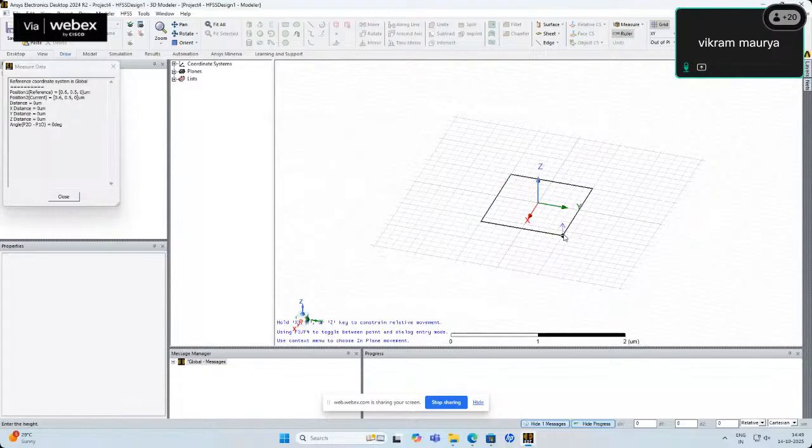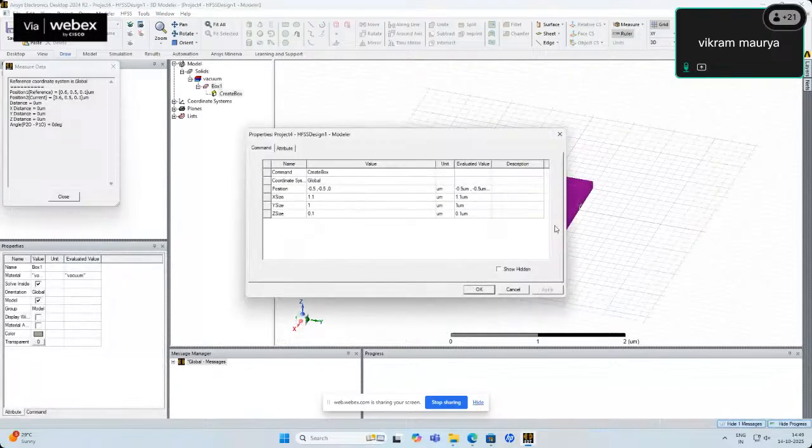Okay, after I click again, now it will tell me to increase its height. The height I can set however I like, but we will be able to change or modify the coordinates as we want later, as you can see in a few seconds. So after I just randomly click on its height, now the dialog box appears. Now, if you compare this to the previous dialog box that we saw, there was no Z size mentioned in the previous dialog box, but there is a Z size mentioned in this dialog box, which means that this particular structure can go in all dimensions. So those structures that we previously saw were in 2D, this structure is in 3 dimensions.